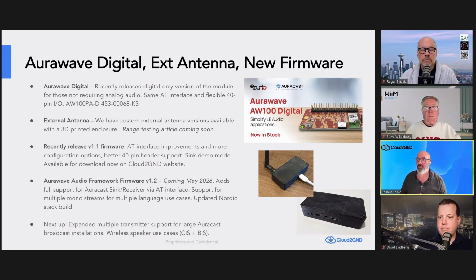There definitely are bridging technologies, such as a mobile phone that can pick up an LE audio broadcast and transmit it back over Bluetooth Classic to my headphones. That's a common example. So there are all sorts of ways you can bridge so that older devices can still be part of the ecosystem. But certainly the driver for this new technology is that it opens up new use cases, so most of this new capability would be LE only.